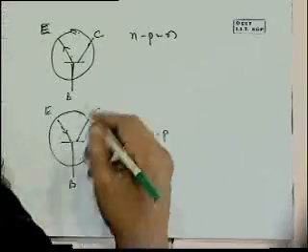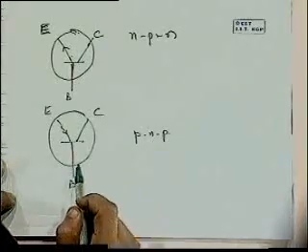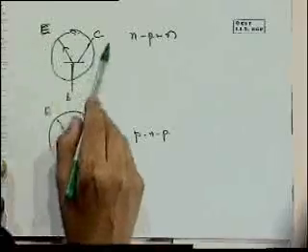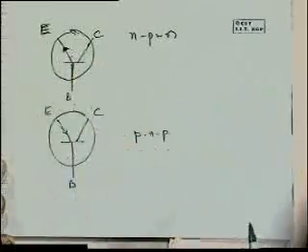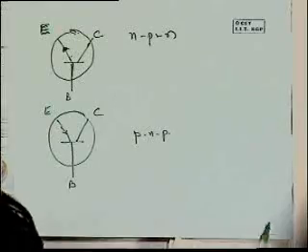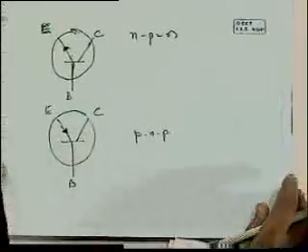Okay, both of these work on a similar principle, just everything is reversed now, and you have holes as the majority carriers in a PNP, whereas in the NPN, electrons were the carriers of the current. So we saw that electrons were transported from the emitter to the collector, and what this arrow is indicating then is the direction of current flow. So that's the basic idea behind the BJT.